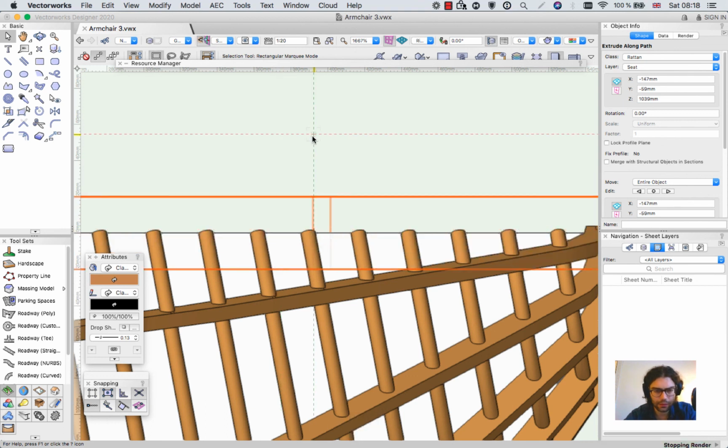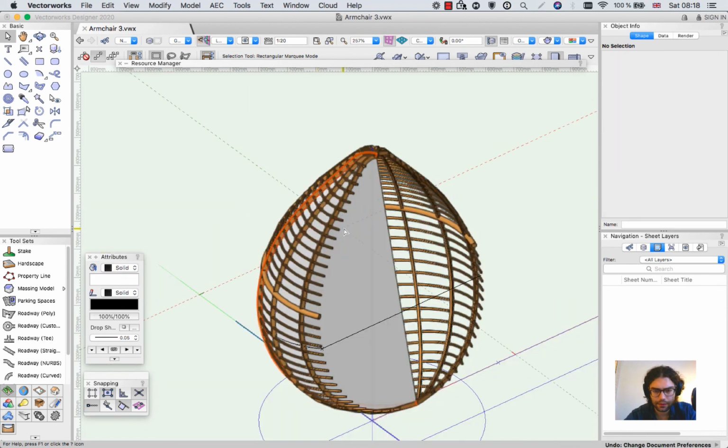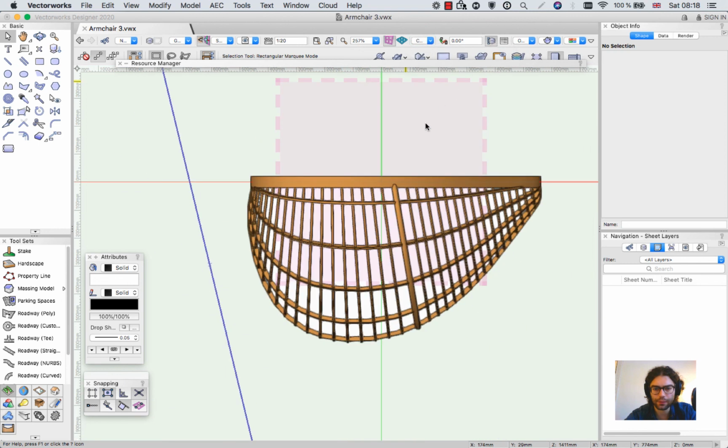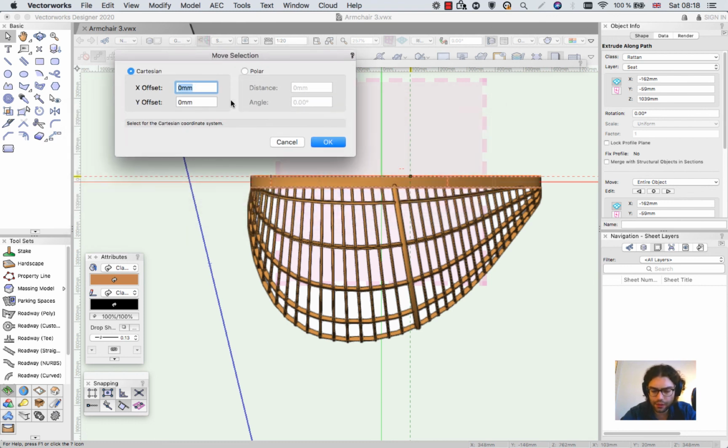You know, I will do it using the move command. So again, set the first, then switch to rotate working plane views and go to the right view. The move command is activated, the shortcut will be Command plus M, sorry. Let's push it a bit to the top.